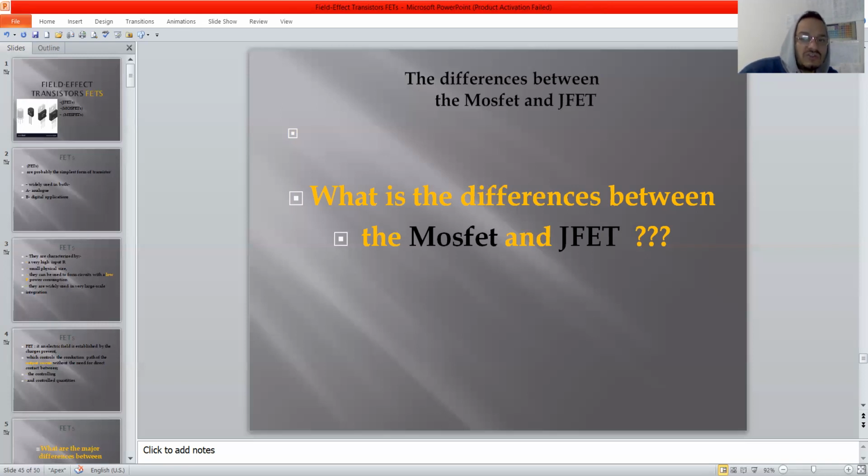The electrons will go on to the drain, to this side, and go to the source. Some change will be at the upper part of the depletion region, just the upper, because at the bottom points, at the last point from these two sides, the depletion region will be the same as at no bias, and the change will be just from the upper points.